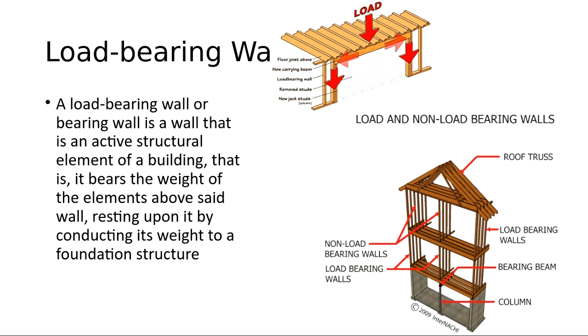So a load-bearing wall, and I covered up my wall thing here. A load-bearing wall is a wall that's designed to take structural loads from the roof on down. So a load-bearing wall is going to take loads from above and transfer them down to the foundation. And we're going to talk about foundations in a little bit. So the load-bearing wall bears the weight of the elements above.